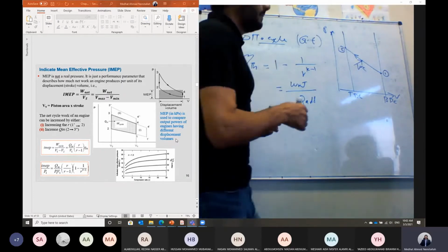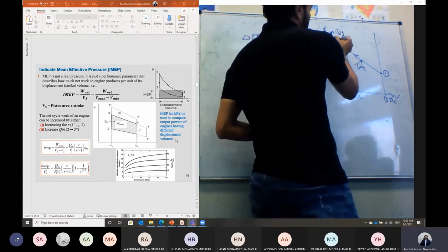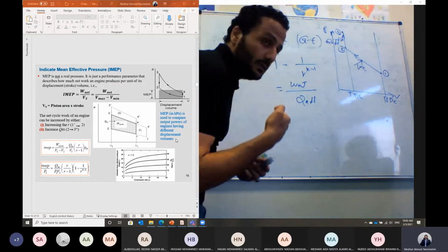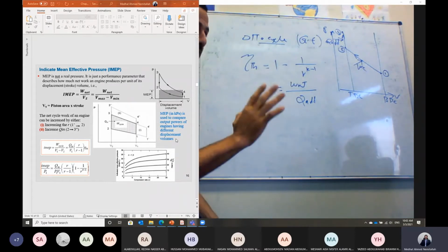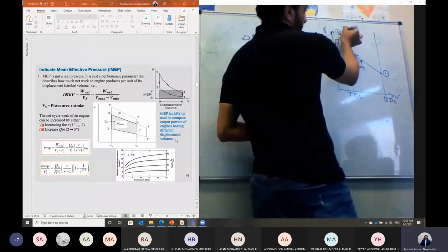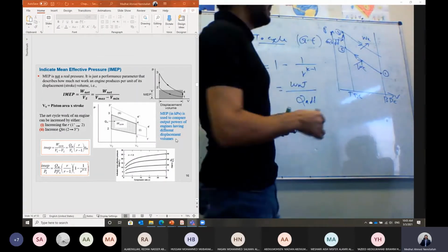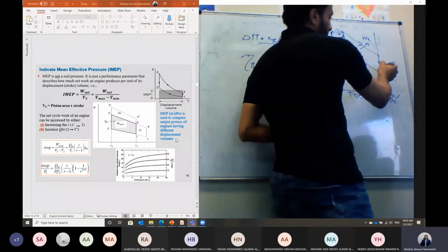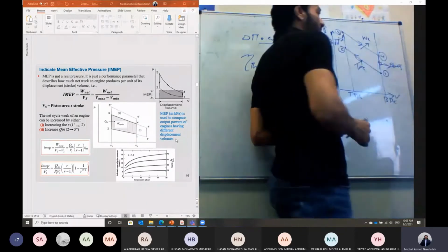And also the process is adiabatic. So we have isentropic compression, then the process from 2 to 3 is a constant volume heat addition. We assume that the combustion takes place instantaneously in the gasoline engine. Once we have the spark, the combustion takes place homogeneously at almost no time, while the piston is at a given location, which is the top dead center. Then after the combustion, we have an isentropic expansion process, in which we can generate positive work, and this process is also isentropic, which is reversible and adiabatic. And then the process from 4 to 1 is a constant volume heat rejection process.